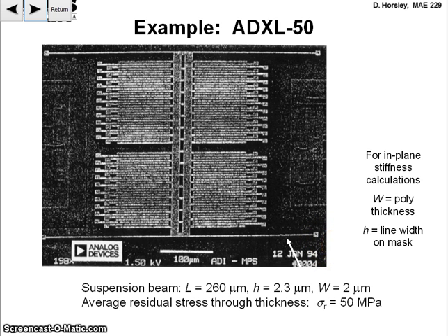So here, what we're doing is calculating the in-plane stiffness, and so the dimension that I said was into the page, I called that B. Here, I'm going to use W, I use B. Okay, so B is the thickness of the film, right? Because remember, we're talking about bending the beam. So here's the anchor like this, and we're talking about in-plane deflections like this. And so this feature here is the width drawn on the mask.